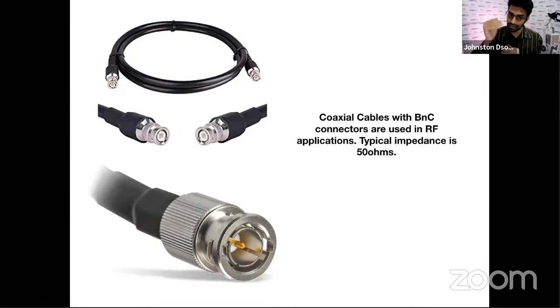Okay. The higher the impedance, the more the resistance to the current and the less the signal flow will be. So we use 50 ohm cables, video guys will use 75 ohm cables. So that's one thing you need to keep in mind, because if you're having long runs of cables and we have a very high impedance, then you will have large signal drops as well. All right.